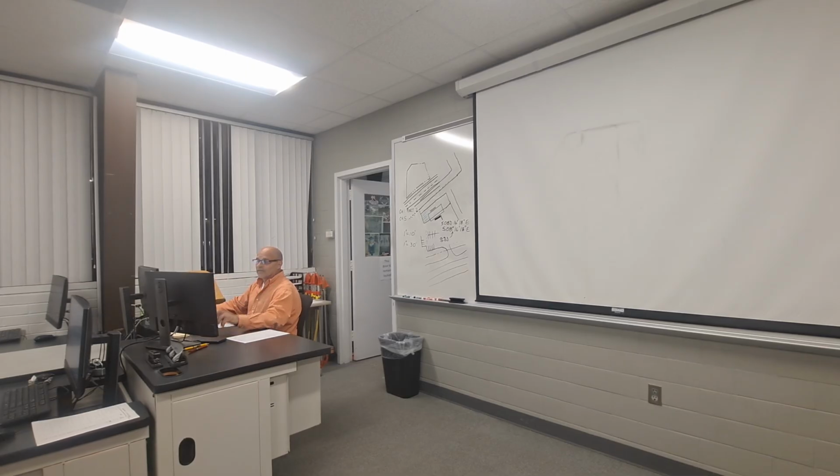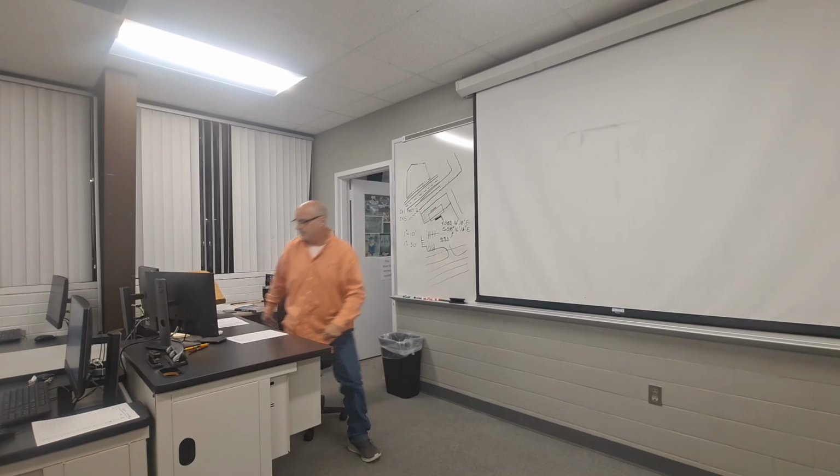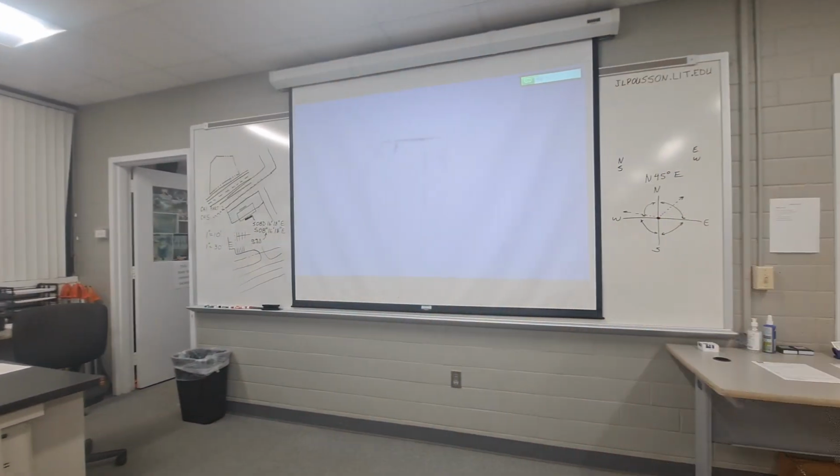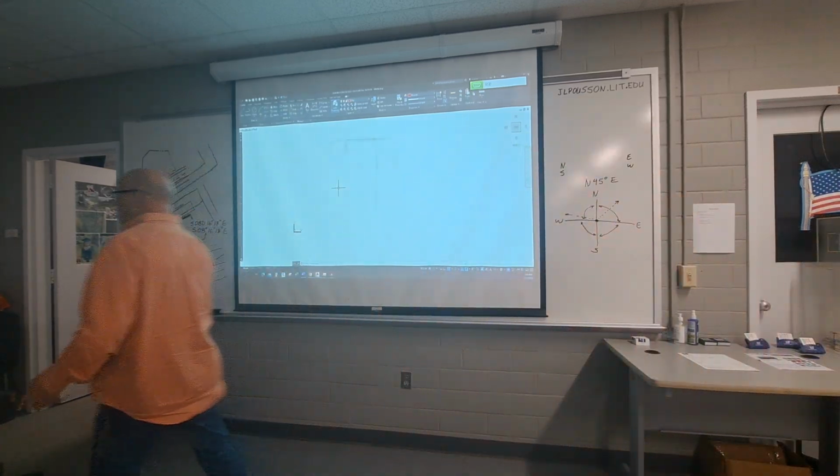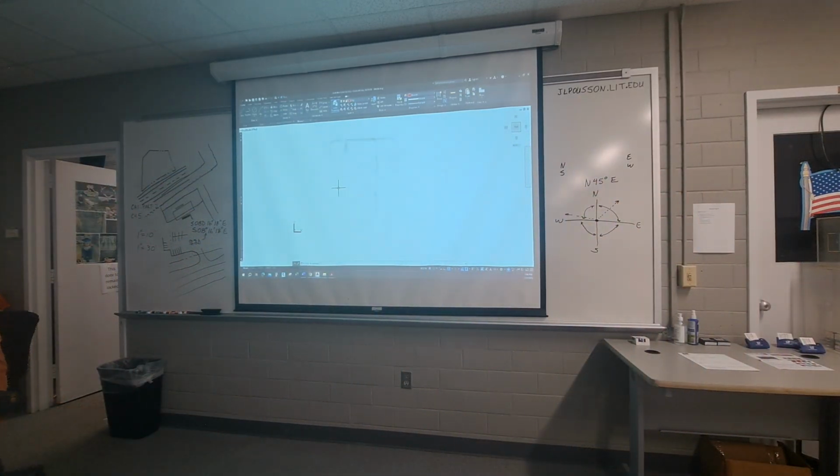So, on your drawing, what I've got opened up here is just my general master. It's got all of the different layers and everything in it. So using your sequence sheet that I put for you in Blackboard, I would open up my master drawing, Control-Shift-S for my save as, doing a property drawing. The first thing I'm going to do is change to my property layer. Now I will be using the relative polar coordinates formula, the distance is less than the angle.